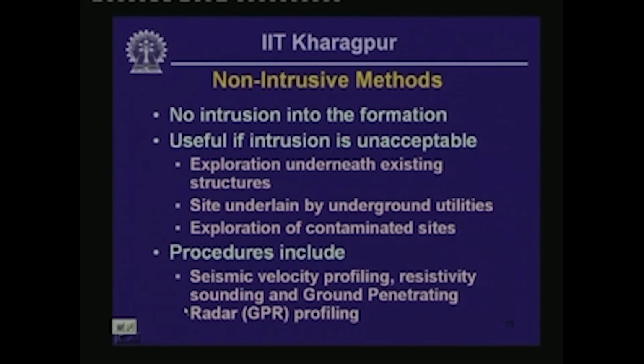Now, we get into non-intrusive methods. Non-intrusive methods involve no intrusion into the formation. So, this technique is useful if exploration has to be carried out underneath an existing structure, or the site is underlain by a number of underground utilities, or exploration requires penetrating contaminated sites which should not come into contact with the devices that would otherwise be inserted into the formation, because then those devices will have to be cleaned up properly, and that could in some situations be very expensive.